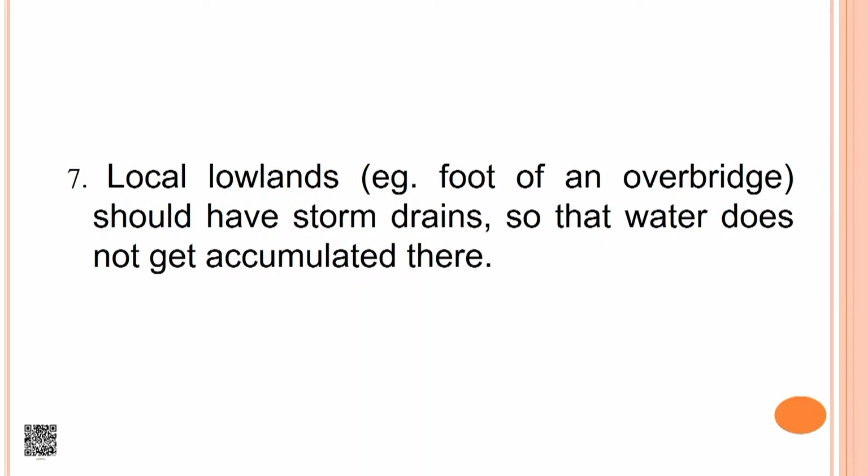Local lowlands should have storm drains so that water does not get accumulated here. These drains should have some kind of mesh covering so that only water can flow in. Leaves and other solid debris should not go into these drains.